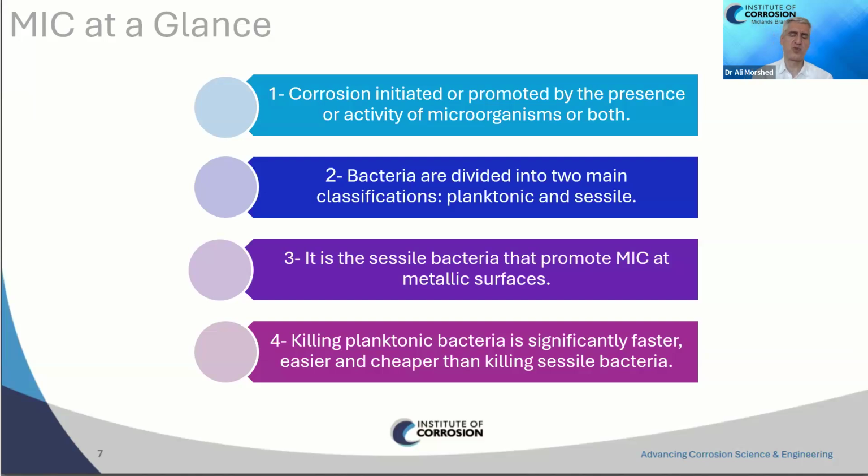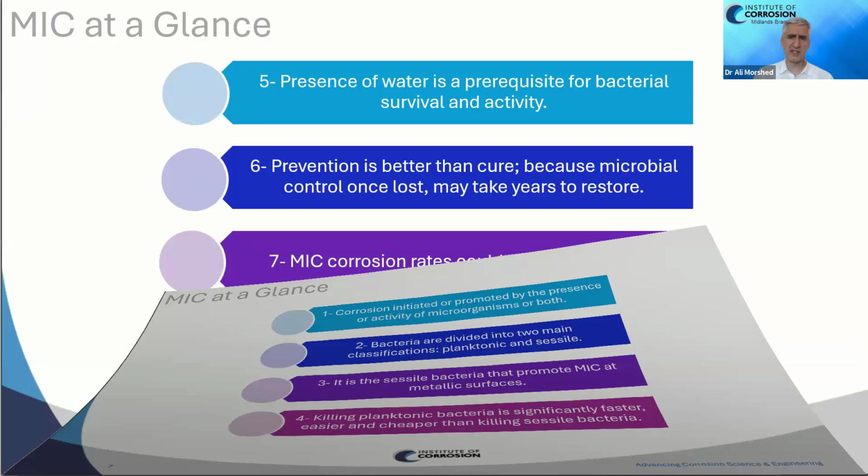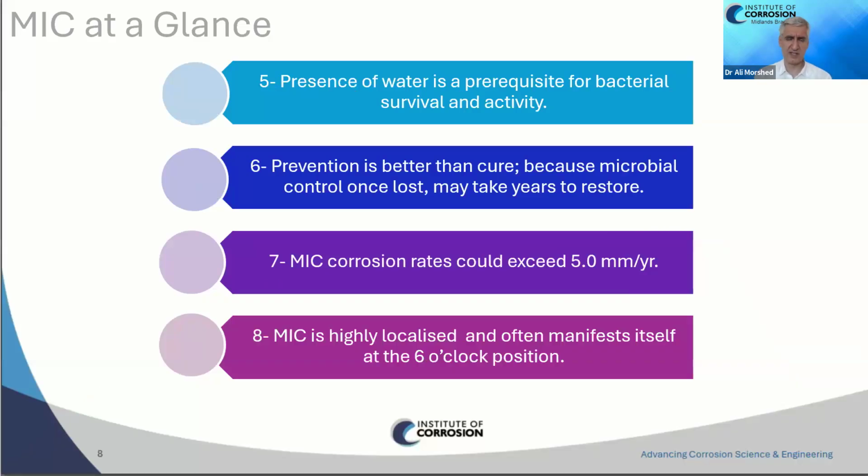Most of us know this point, but what has been surprising me over the years is that many oil and gas operators which have to deal with MIC, unfortunately, still do not distinguish between sessile and planktonic. And in some of their companies, the policy designed to mitigate MIC only covers the planktonic bacteria, which is, as I said, faster and easier and cheaper to kill than sessile bacteria. Their corrosion management protocols are all formulated based on planktonic bacteria. They do not take into account sessile bacteria.